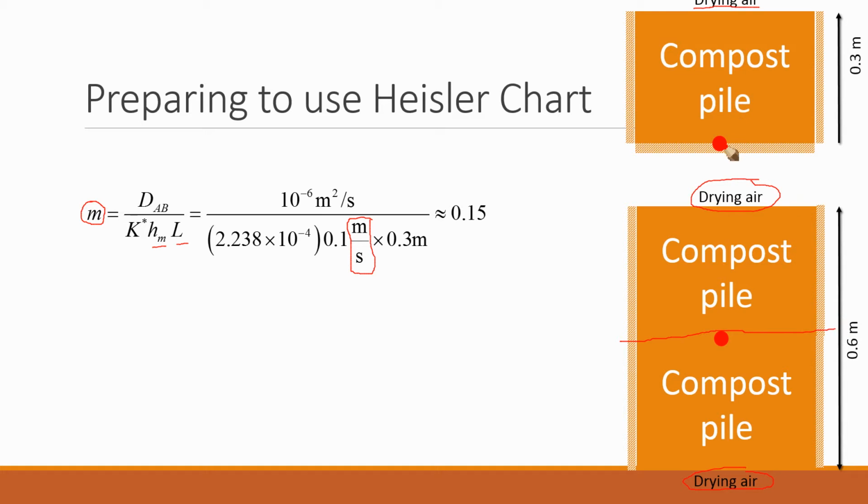So this impermeable layer really corresponds to having a slab twice the size, but dried symmetrically from both sides. In that case, the center boundary would be same as the bottom boundary now. So these two problems are equivalent. And because we did this one, and for which 2L was 0.6, then the L we need is 0.3. So that's how we get the L equals 0.3.